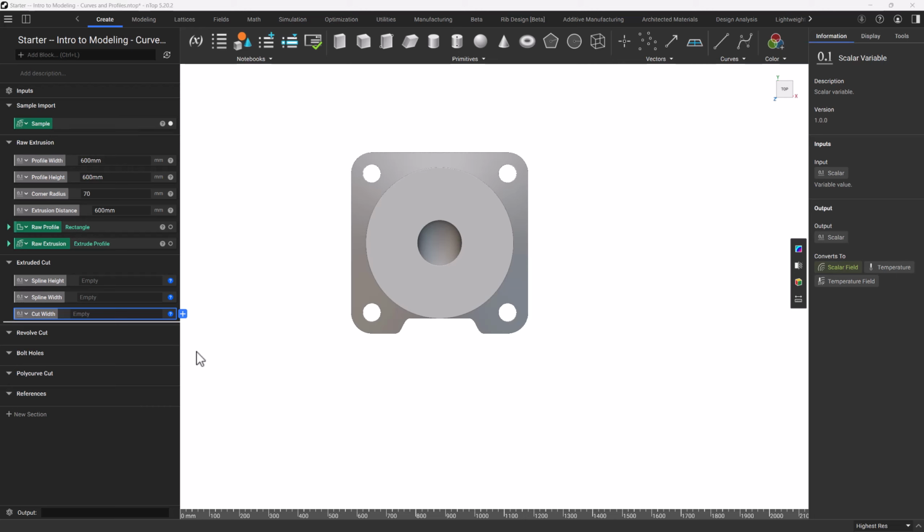We're also going to create two more variables that are actually dependent on some of the variables we've already created. This is going to be the straight line width, or the width from where my fillet begins on one side of my rectangle to the other, and then also the offset from this fillet begin point here to where I want my spline to begin.